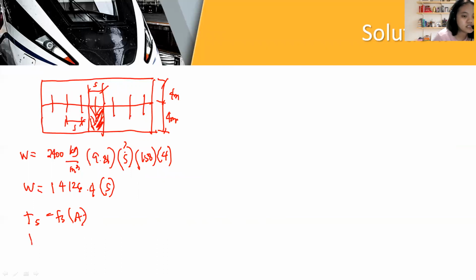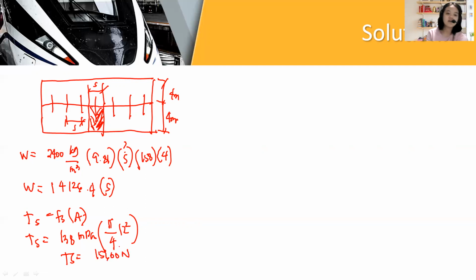Okay, so yung tension force natin, yung tension stress is 138, tama ba? 138 megapascals multiplied sa, multiply natin sa kanyang area ng 1 bar. That is pi over 4, 12 squared. Okay, that is your tension is equal to 15,600 Newton.